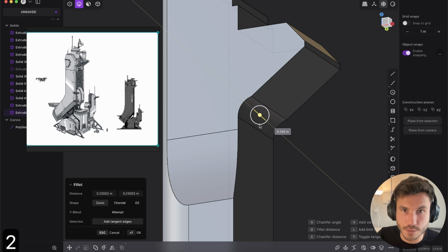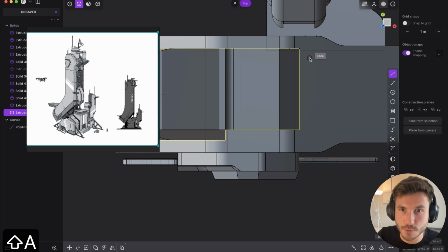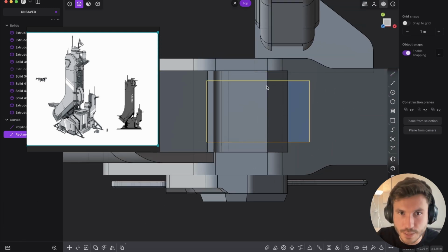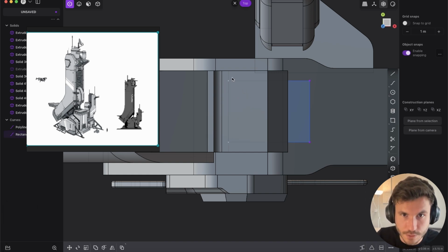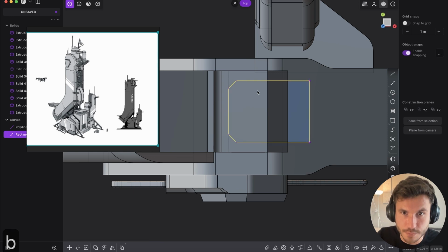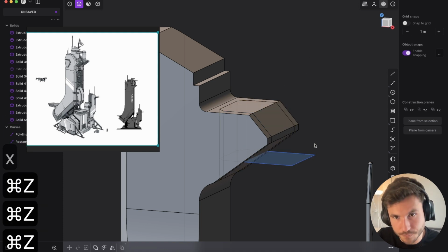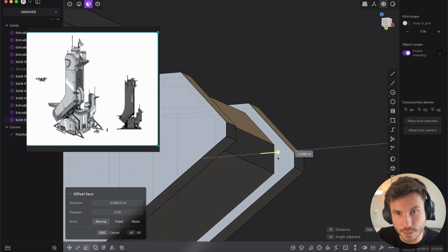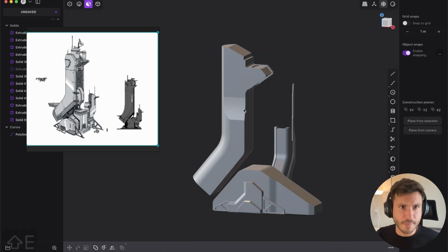Now let's connect this with a nice fillet. And from the top view, create a rectangle around here the center and press C. Give it a rectangle and select those 2 points, and give them a chamfer and cut into this main body. And yeah, maybe you don't have to delete that. You can now select those faces here and just bring them maybe inside. And this chamfer make a little bit bigger. So yeah, you have something like that.